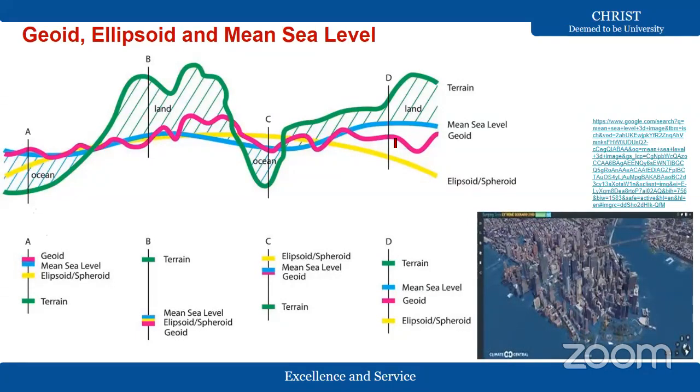But in GPS, you might know a little bit about GPS, it gives the elevation data with respect to the ellipsoidal height, the ellipsoid or spheroid height. This we won't consider if you become a technocrat after your BTech. So be careful about GPS measurements. You need to convert the GPS heights to the mean sea level.